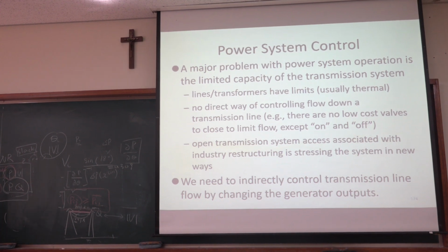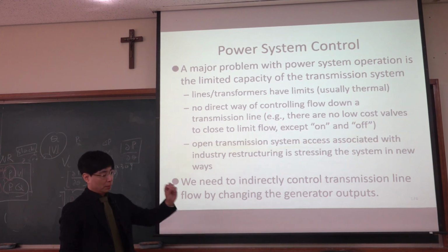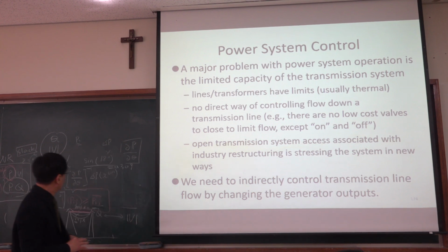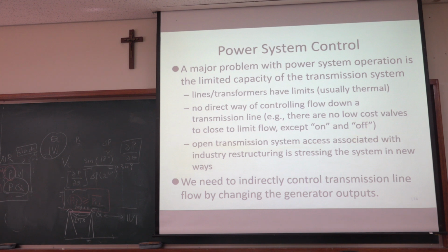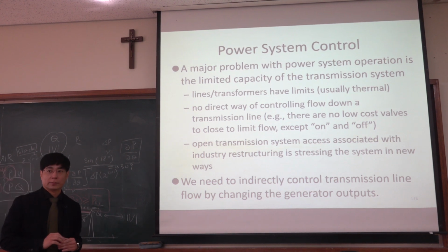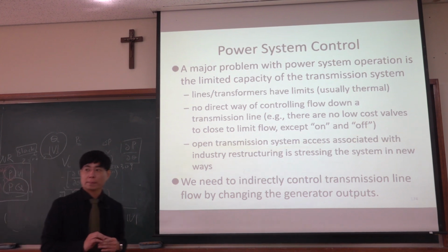Before you solve the power flow equation, the generator output is already determined, like the maximum or just 80% of the generator. We have hundreds of generators in Korea. The output power of the generator is determined somehow. But when you solve the power flow equation and find that some line is congested, then you need to adjust the generation amount. And that's why KPX or the ISO first needs to solve this DC power flow quickly to check whether some line is congested or not. Of course this is an approximate solution, but anyway, it is good to check whether some line is congested or not.